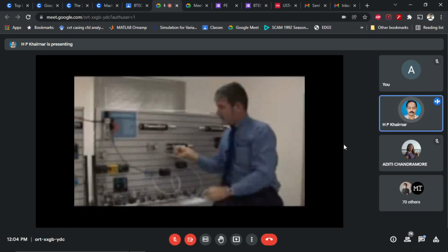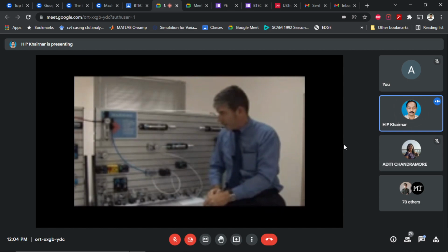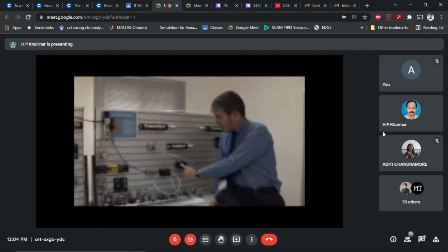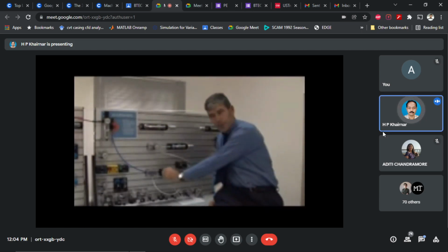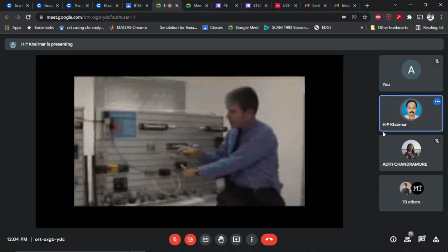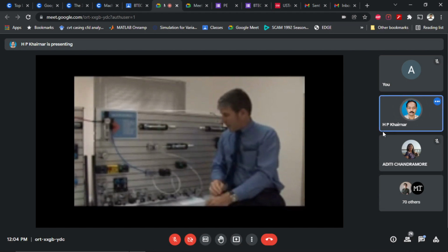And our pressure gauge here will give us an indication when we've got air supply into the cylinder. So now if I connect it, I'll switch on the supply. And if I press this button, nothing happens. But if I turn on our master supply here, press the button, we get the cylinder extend and air pressure shown here, which then drops.